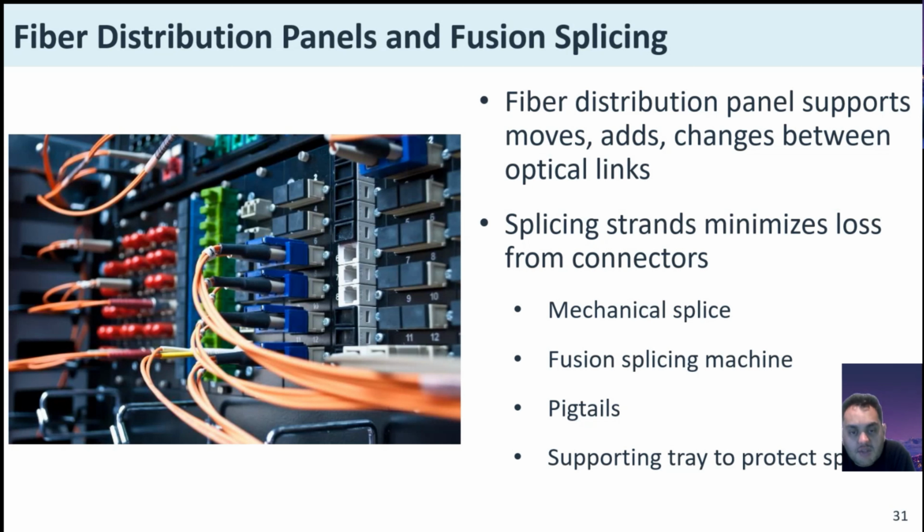Splicing may also be used to attach a pigtail, a segment of cable with a factory-fitted connector at one end only, or to field terminate to a connector, splicing a factory-prepared SC or LC connector to an incoming cable.